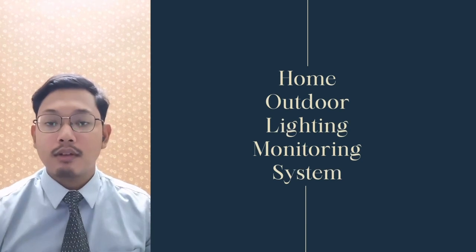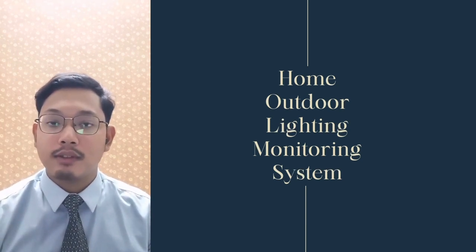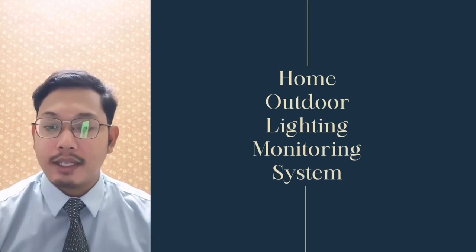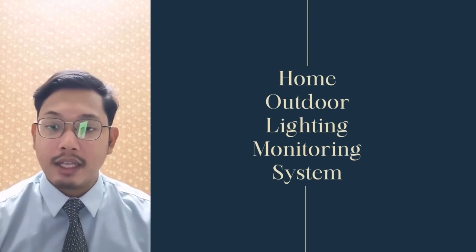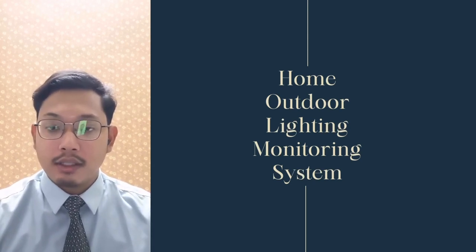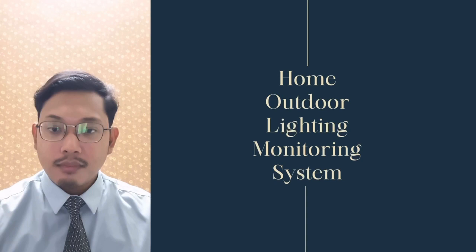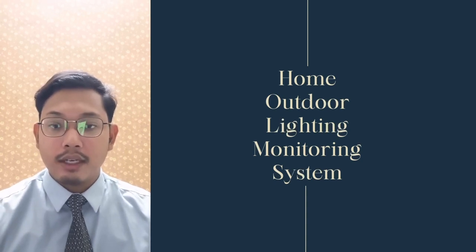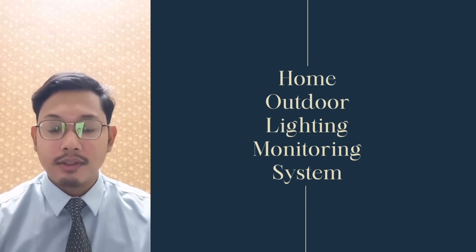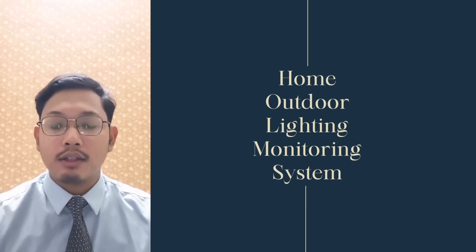So, how does the system work? Let me explain. The system works by using an LDR sensor that can detect the presence of light in the surroundings. For instance, if the outside is dark or at night, the LDR sensor will detect there is no presence of light. So, the system can turn on the light automatically and vice versa.